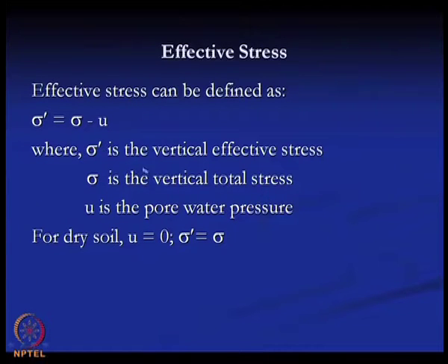When we apply a weight or load, that is a stress, on a soil, initially this stress is taken by the water. If we do not permit any flow of water, the stresses will be taken by the water in the initial stages. Now, if we permit the water to flow, then gradually the water will flow out, and the stress which was taken by the water initially will be transferred to the soil skeleton. So, as time progresses and the water goes out, the soil will take the stress in that fashion.